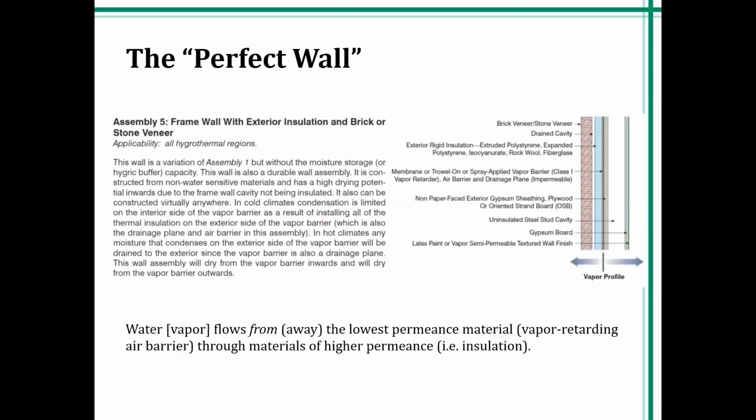So if we were to use this wall or even this wall, and we were to specify a vapor permeable air barrier in a particular climate zone that is prone to higher amounts of precipitation, the fact that we have exterior gypsum sheathing, which is water resistant, and we use an untaped XPS insulation, reverse water vapor migration, say on a hot July day, we're dehumidifying on the building's interior to about roughly 30% RH and effectively 100% RH on the outside. We can have water vapor migration through the untaped joints, presumably, and possibly into the gyp sheathing.